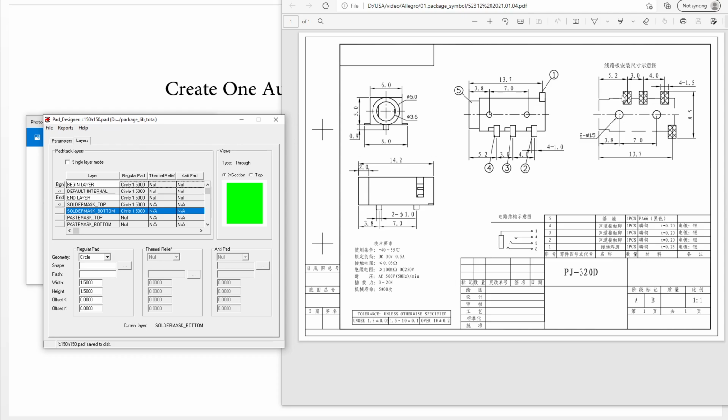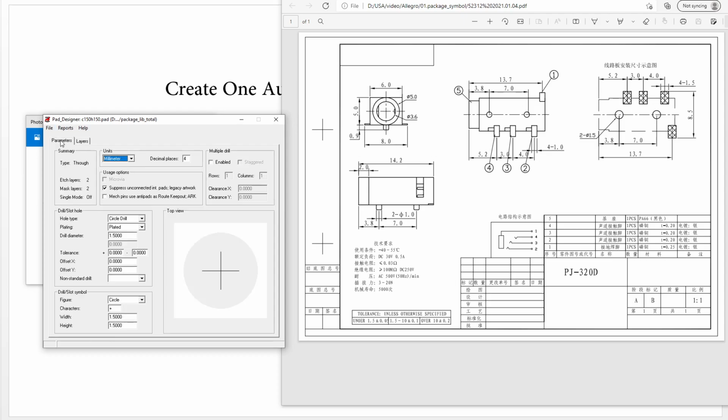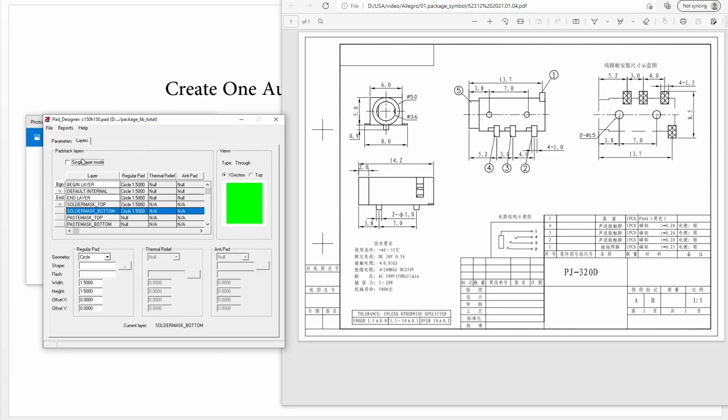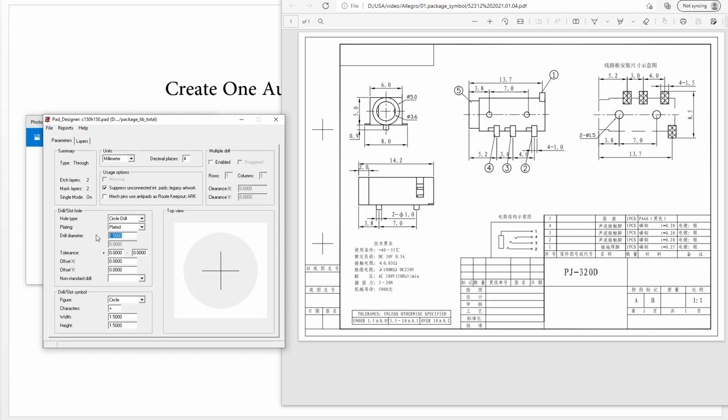And the second one, we need to draw this pin, this pad. We need to design this pad. Okay. So for this pad, we know the width is here, so it's 1.5, and we need the drill hole. Okay. We don't need to drill anything because it's a single layer. It is a single layer, and we don't need to drill anything.